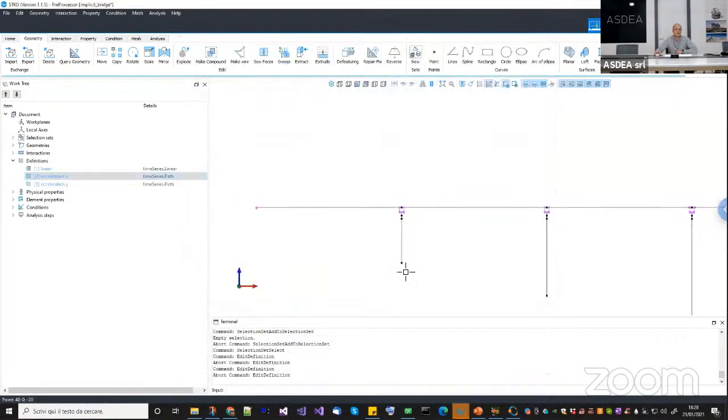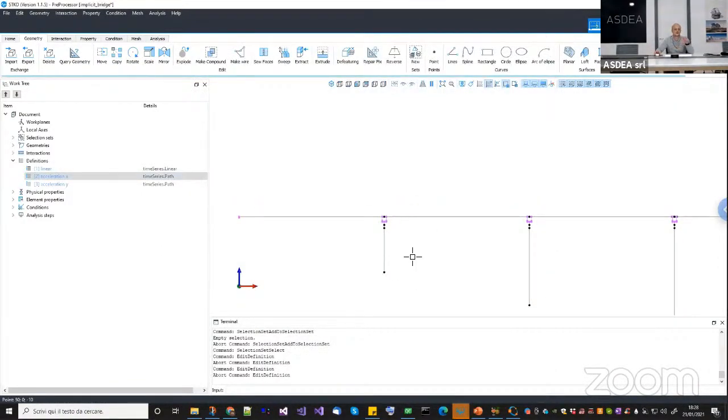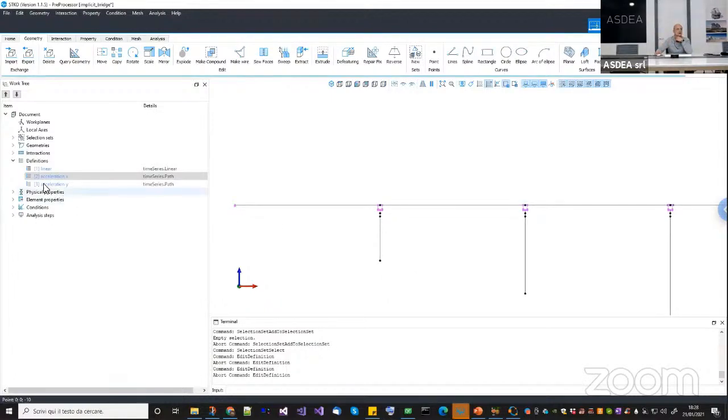Oh, by the way, I forgot to tell you, but for those of you who are new to STKO, STKO is just like OpenSees, is unitless in the sense that you don't have to define a unit system in the software, but you have to know what unit system you are using because you have to be consistent with the values that you input. In this case, I'm using kilonewtons and meters, okay? So just to let you know what unit system I'm using.